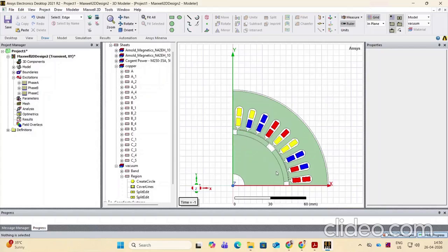If the number of poles in the reduced model is odd, then the polarity of B on the independent axis would be just the opposite of the dependent axis. Therefore, in those cases, B independent will be minus B of dependent while configuring the dependent boundary.